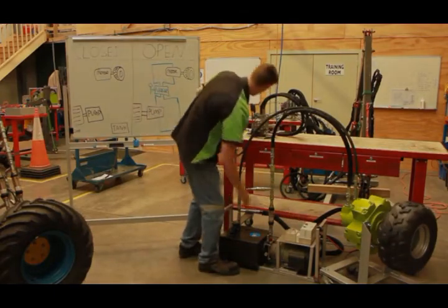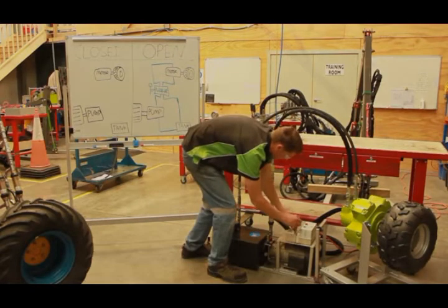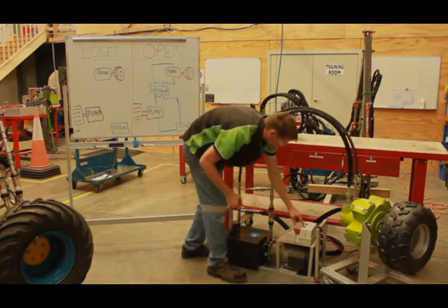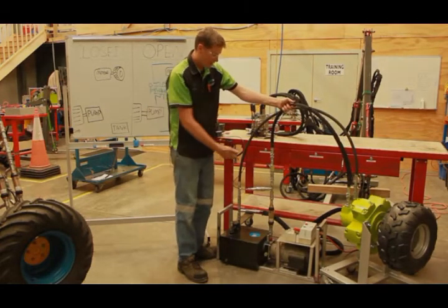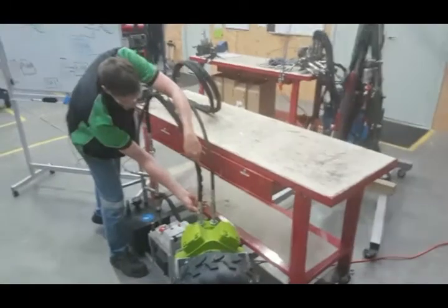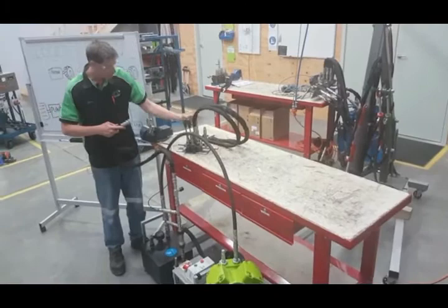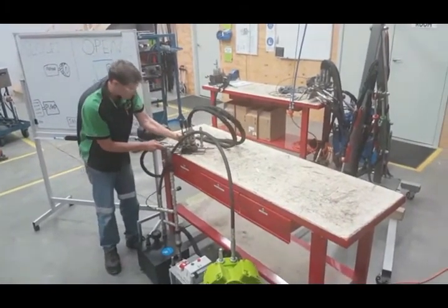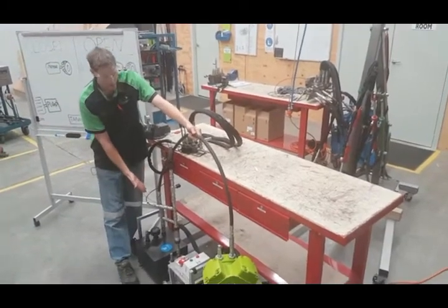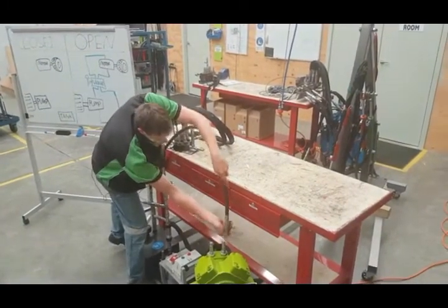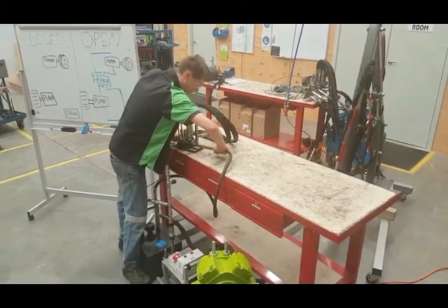I'm going to do that here now. I'll stop my pump, I'll isolate it so that I'm nice and safe, test my isolation, and then I'm going to take the hose from the outlet of my pump, remove it from the motor, and install it into this directional control valve that I've got set up here, into the P port. I'm then going to take the hose here, which we can see returns into the hydraulic tank. I'm going to remove it from the motor, and install it into the other side of my directional control valve.